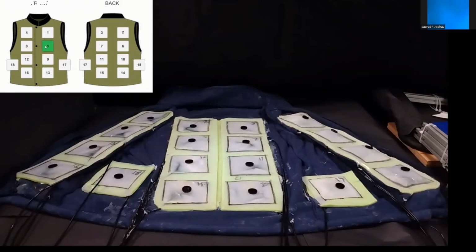The deflation of the pouch is accelerated by generating vacuum using the fluidic logic module corresponding to the pouch, rather than only relying on the elastic restoration force. Here we control 16 independent pouches using just 8 solenoid valves.